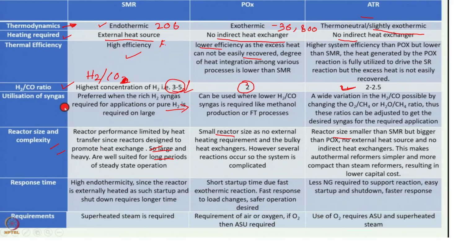Okay, and response time is important. In the SMR reactions, the response time is very high. It is not dynamically very strong, but here the time is very short and it is dynamically very strong. I mean fast response reactions. That means here you require very high temperature and a burner. You require a sufficient amount of heat, then only will the reactions occur.